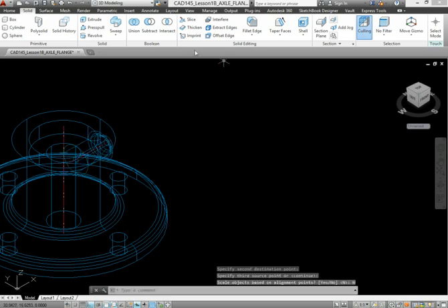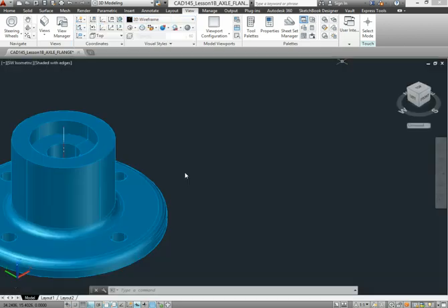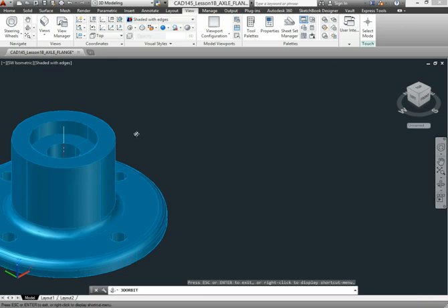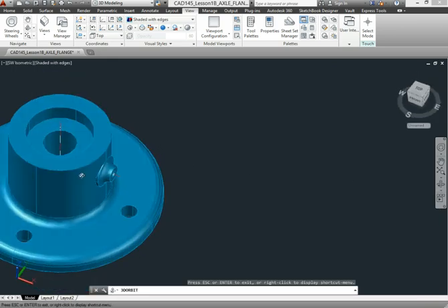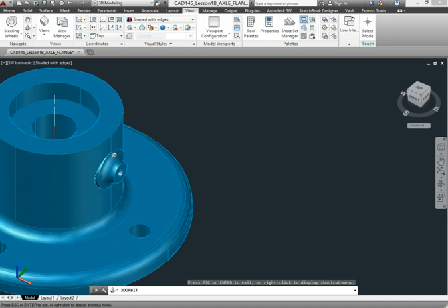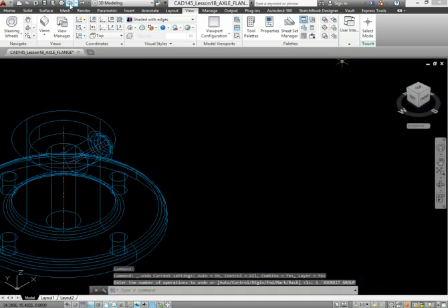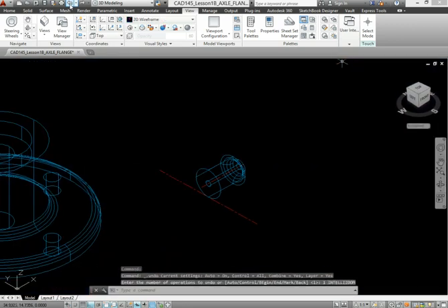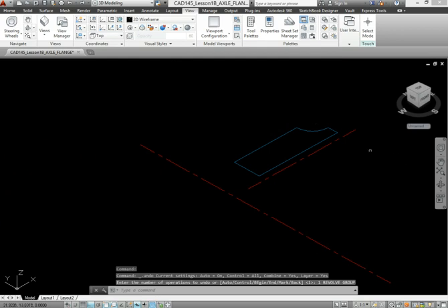Okay? Now that that's done, I'm going to show you why this was incorrect. Let me rotate the block using orbit. See the flaw? That shouldn't be happening. So I should not pre-fillet this. I need to do that after I move it into place. So let me show you the correct way of doing this. Let me undo the steps. Back to our two-dimensional part. Okay.